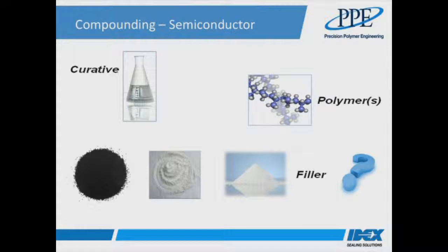So we've seen that there are various basic polymers, FKMs and FFKMs, and these are often fundamental in determining the properties of the elastomer. I just want to also discuss in a little bit more detail some further additives referred to either as reinforcement systems or filler systems. If you've come across elastomers or O-rings in the past, you may have noticed that many or even most of these are black in colour.